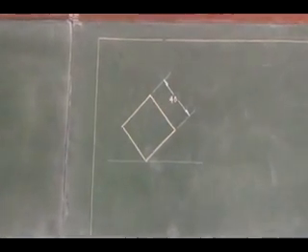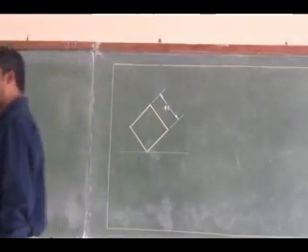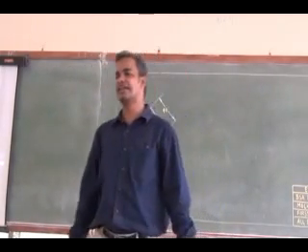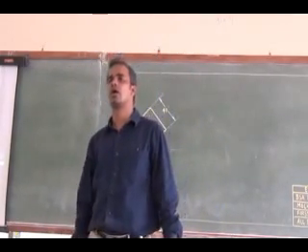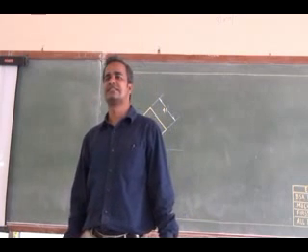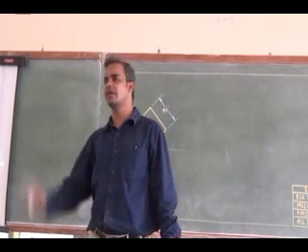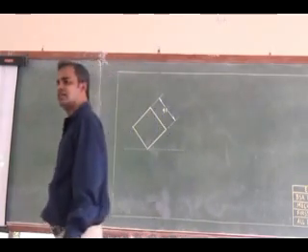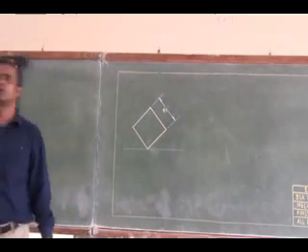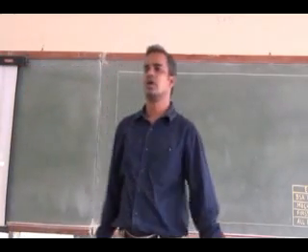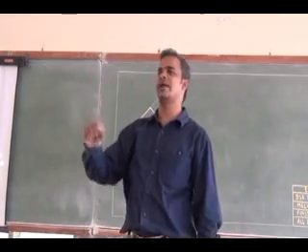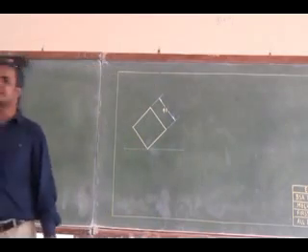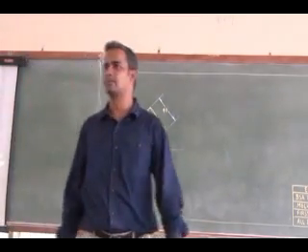Read fast. Construct a regular pentagon of side 30 mm in such a way that subdivision 1, a side of the pentagon is horizontal.